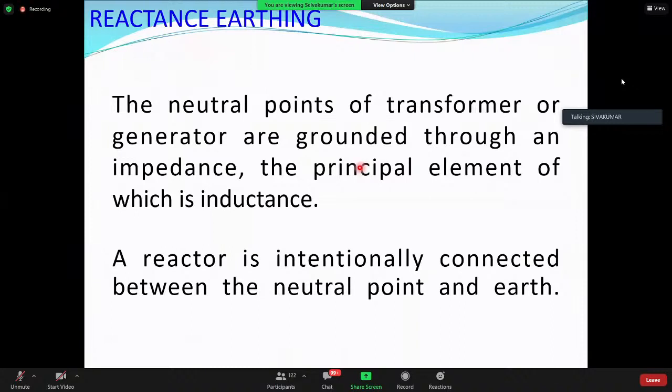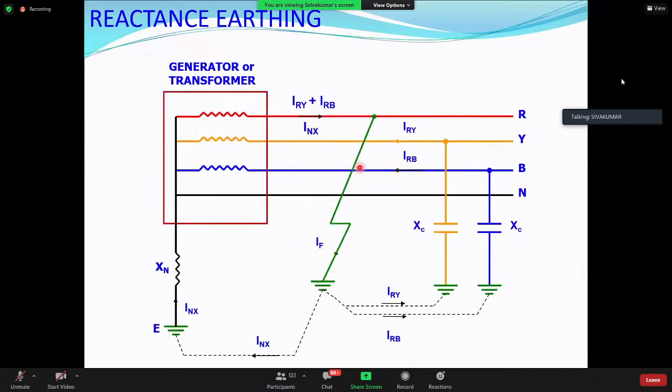Now assume the ground fault current is the phase to neutral voltage divided by the impedance you are going to put. The higher the system voltage, the higher the phase to neutral voltage. Let us say you want to limit the fault current to 400 ampere. If you put the equivalent ohmic impedance in the ground path and it is resistive, then it will cause more heat.